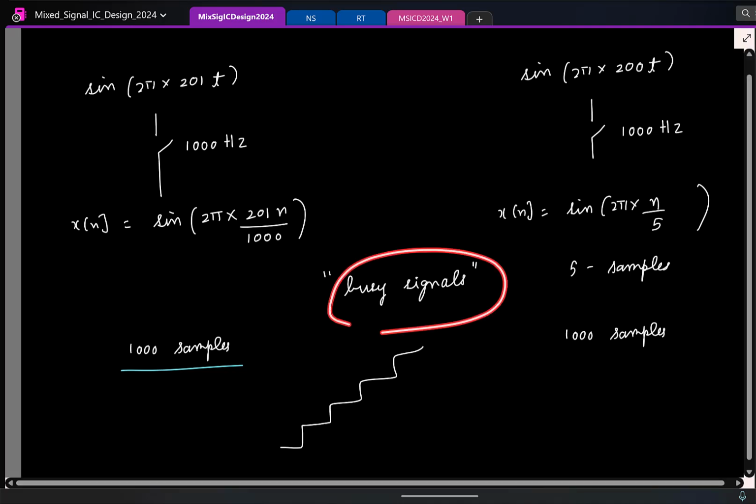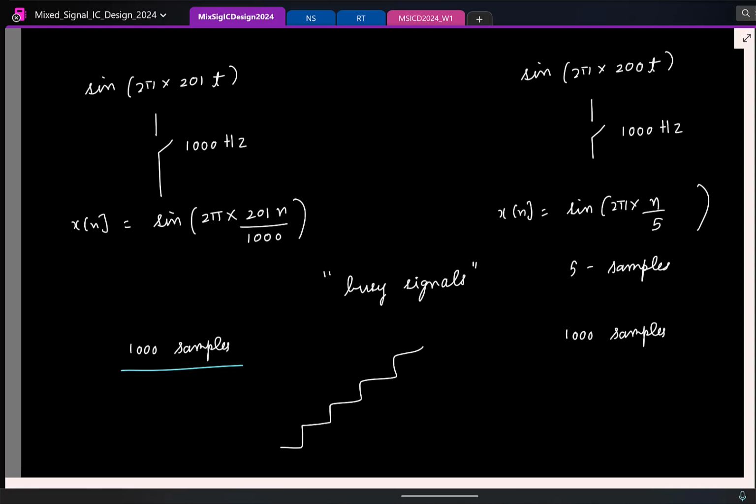As long as we have these kinds of things, it looks like the quantization error PDF is almost uniform. Okay. It's called BC signals technically. I'm not going into a lot of rigor here. You just assume that it is a case where the signal spans the entire range, exciting all quantizer levels, and there is sufficient variation from sample to sample.